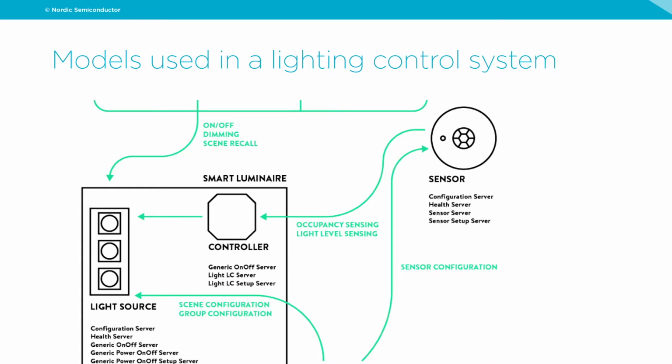With Bluetooth Mesh, and this is basically related to the electronics that go into the luminaires that support the technology, they are so powerful that this lighting control box is no longer needed. You can do these calculations in the light itself. So you actually eliminate the lighting control box. You do it on a luminaire and you control the light source.